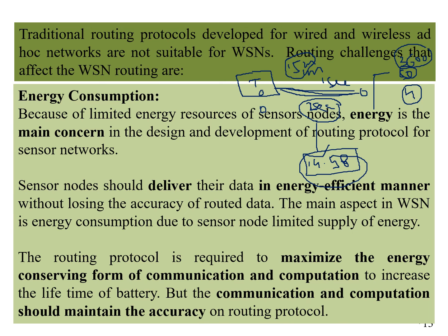So what we're going to do to save the energy is keep this node in sleep mode for that much time. When this node is in sleeping mode, it will not use much power. It will use the power only when it needs to send the data, and that time will be 2 seconds.